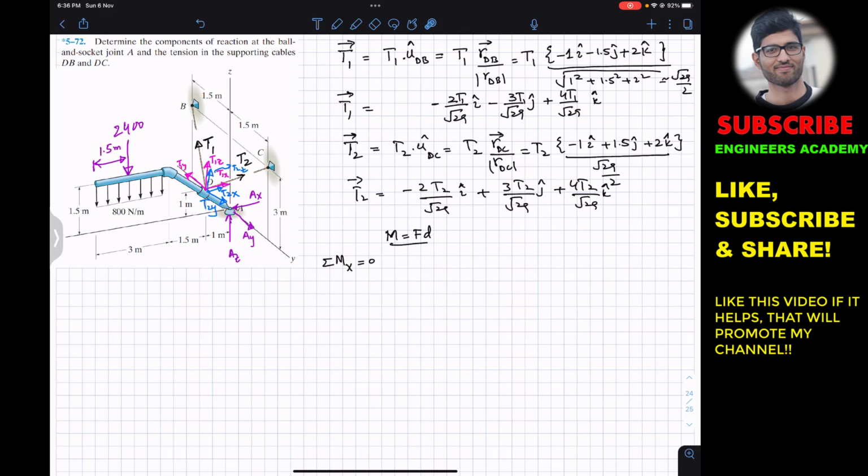Now if we look at T1y, it is going to produce a moment about the x-axis in this direction. If we curl our right hand fingers in this direction, the thumb will point out in the positive x. So this means that T1y is producing a counterclockwise moment. So you will write plus T1y, and the perpendicular distance of T1y from the x-axis is 1 meter. So 1 meter is the moment arm of T1y, and I will multiply this with 1.